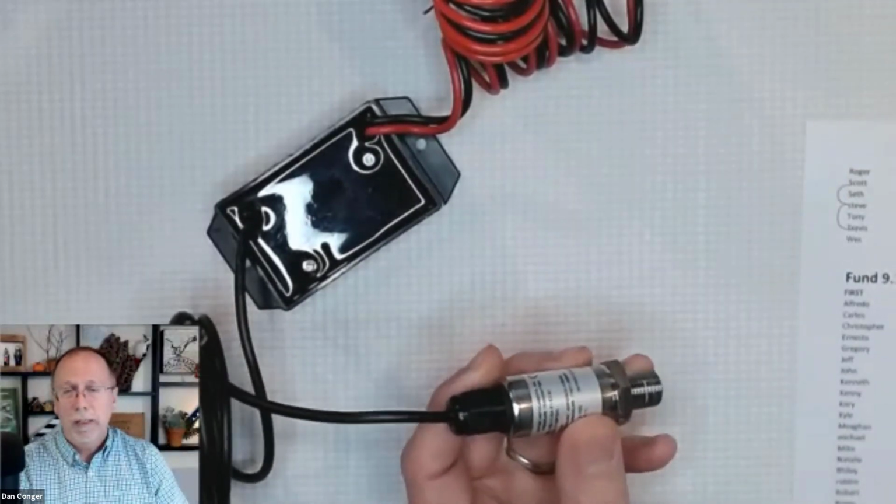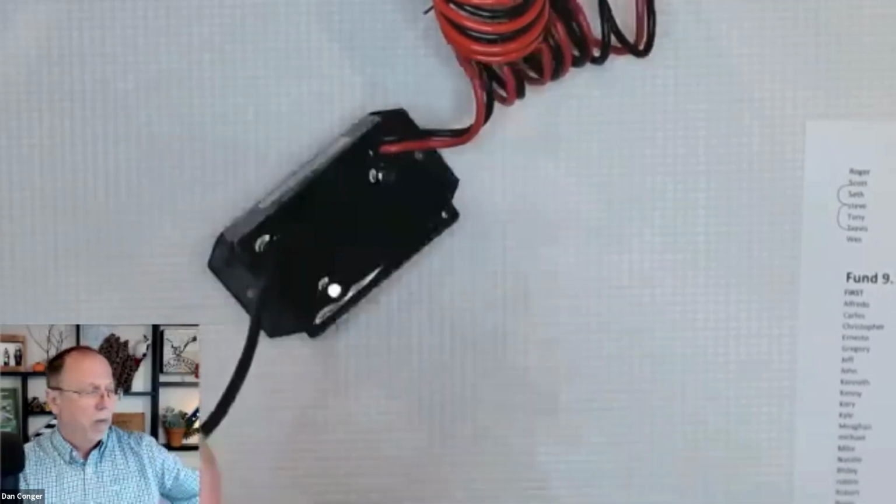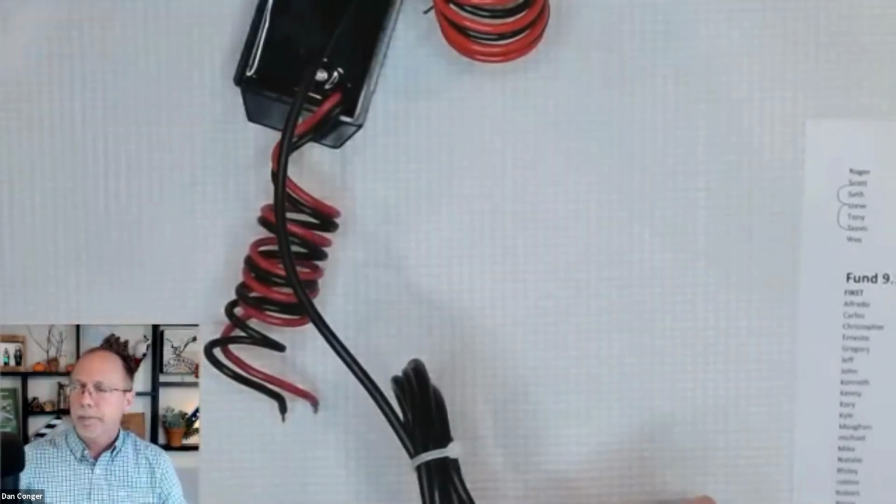Now, if you change this to a lake transducer, a 0 to 5 PSI, those are intended to be suspended, to just hang like this. The only thing that's really different is a little protective cap. When I ordered one, the only thing I realized is it's the same thing. It just comes on a different cable, has a vent tube, and has a plastic cover to keep crap from getting in. It's identical. It's got the same thread. So if you were using this device, I would recommend threading it into a fitting that's accessible. I would probably not set it inside the tank, or you could drop one in and just hang it suspended. I think ultimately the difference between this and a lake level transducer is how you are going to mount it, because if you didn't have the ability to thread into a fitting, you might have to hang it and drop it in.